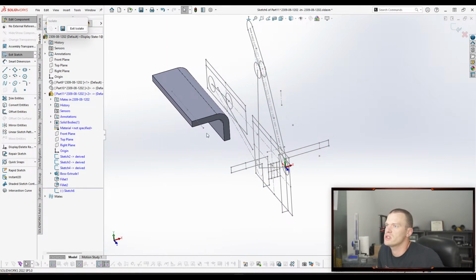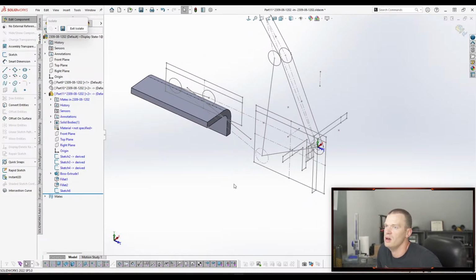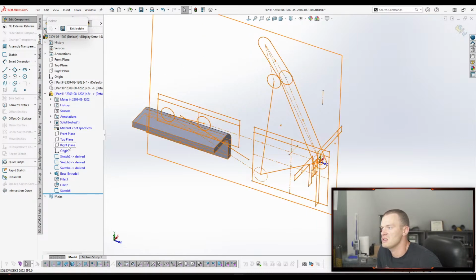So in this, we're just going to create a sketch that has these 3 points in it, and we're going to use a sketch-driven pattern later to orient the holes where the bracket gets mounted. So these are going to be holes for a flathead screw. And what we learned in the morning session is that it's a non-standard hole.